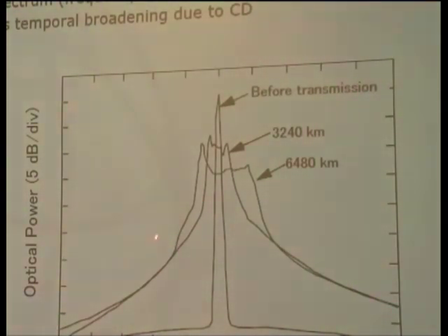The phase modulation is caused by the self-phase modulation, a nonlinear effect. So this is problematic because such a broadened signal can suffer from the chromatic dispersion distortion, because the signal boundaries became so wide. So it can be easily affected by the chromatic dispersion. Okay.